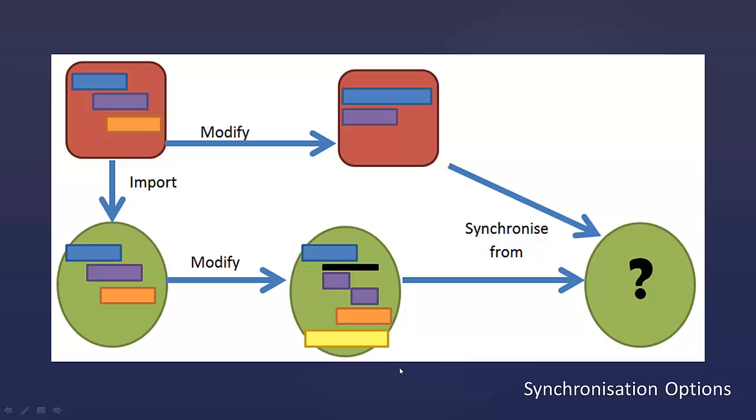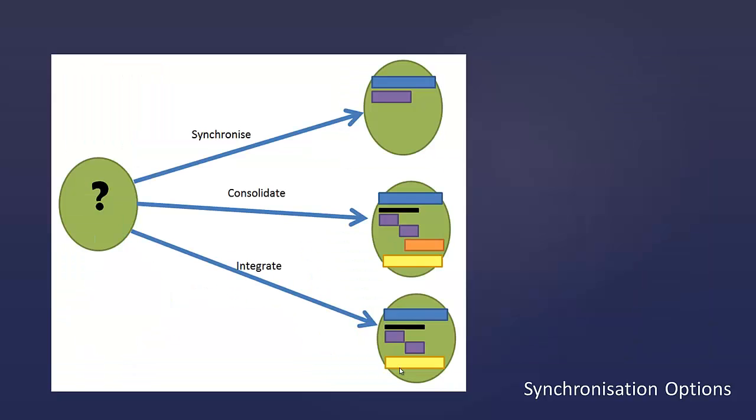Meanwhile, in Synchro, we're going to modify. We added those subtasks. We added an extra task for animation. Also in P6, we made some changes. We deleted a task. We changed a duration. And when we go to Synchronize, the option that we choose is going to affect what ends up here in Synchro, whether that's Consolidate, Integrate, Skip, or Synchronize. It's going to change what we result in Synchro. So here's how that works.